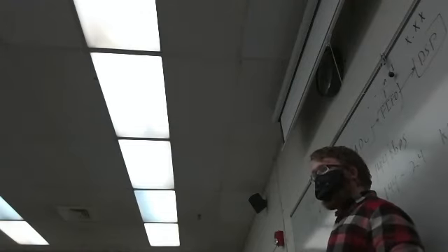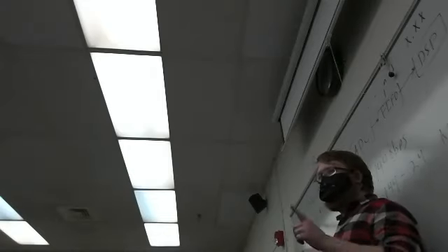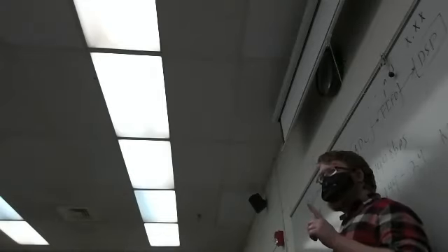Which we need the, wait, hold on, you need the number of bits in your FIFO. Yeah, isn't that 48K? Wouldn't you want to, because you have the 12 in there already, make it the total space in it? Yeah, so the total space is a width of 12 and a depth of 48. So would we need to convert that back to samples?